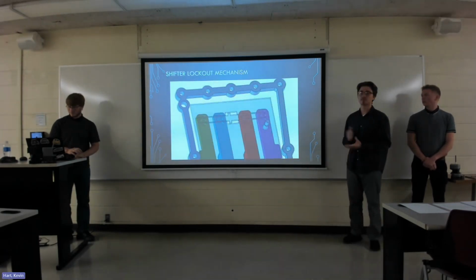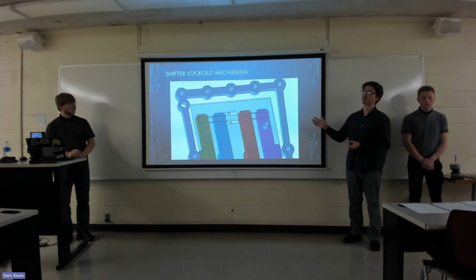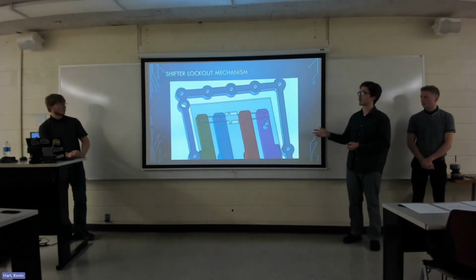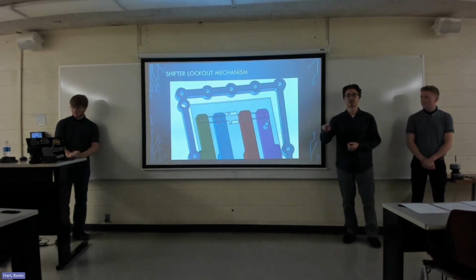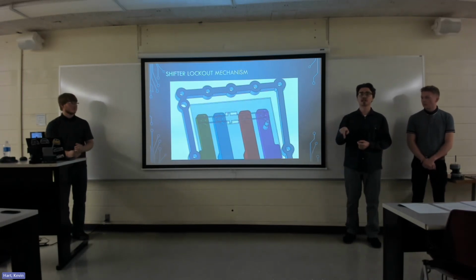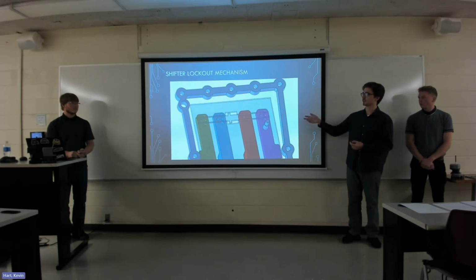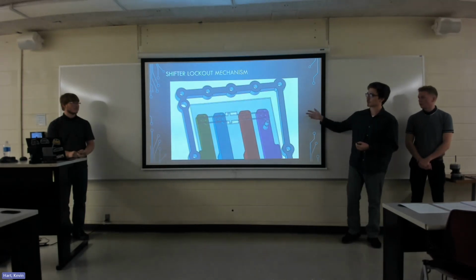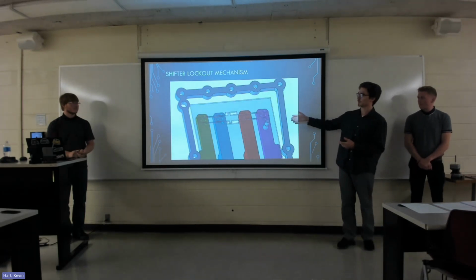And going on to the lockup mechanism, this criteria actually satisfies one of our constraints where we can't have two simultaneous gears engaged. Right now, the twin cams actually cannot engage at the same time, but this lockup mechanism prevents any gears from simultaneously engaging.